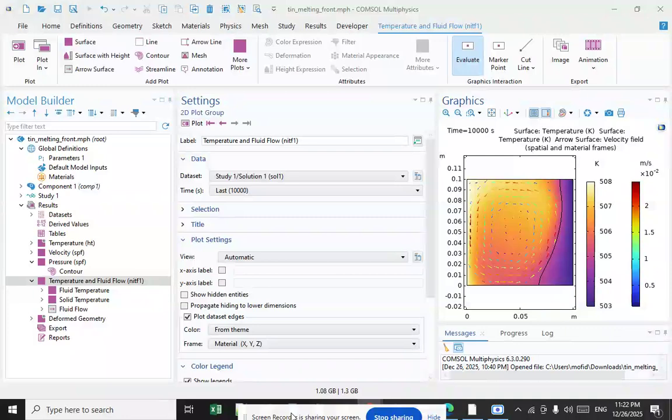There are also a number of phase transitions involving three phases: a eutectic transformation, in which a two-component single-phase liquid is cooled and transforms into two solid phases. The same process, but beginning with a solid instead of a liquid, is called a eutectoid transformation.